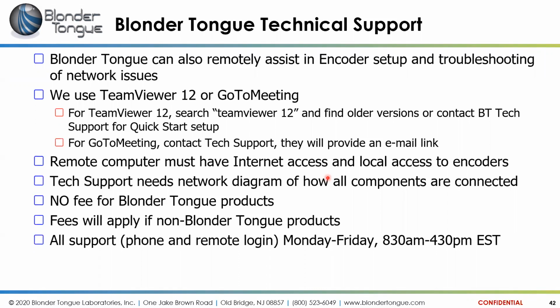So if your encoders are not on your local intranet and they're just standalone, you would need something like a laptop that you can hard line to an encoder and also have Wi-Fi on the laptop going out to the world, so that we can come in through TeamViewer or some other method into your laptop and then go hardwire from your laptop to the encoder to be able to help set you up and troubleshoot. Again, no fee for Blonder Tongue products.